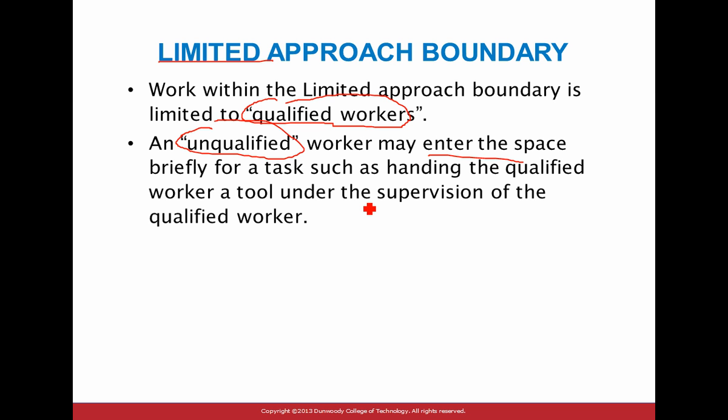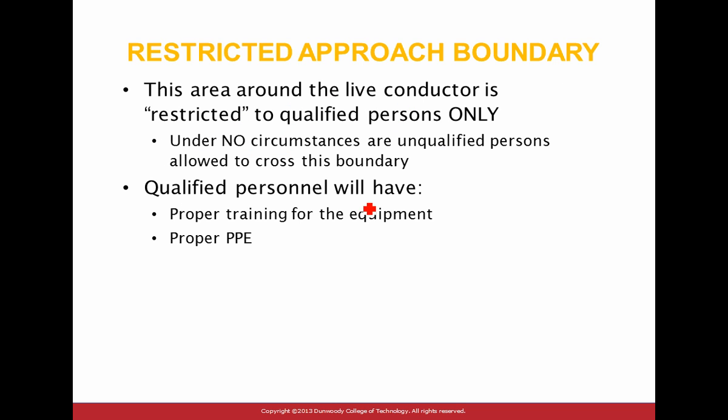You're not qualified, so you can enter to give me a tool and leave. The limited approach is me working on equipment. And remember, the prohibited approach is the tool. If you're unqualified, you have to be supervised and escorted when you get in.